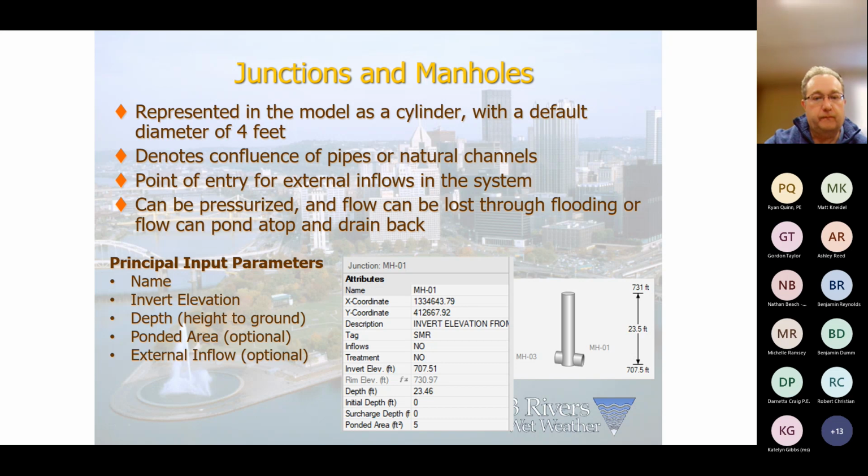When you're working with storage nodes, it has a single place where you mention the rim, so to say. So there you are going to work out your surcharge depth and then put that as your manhole depth. So there are no distinct parameters for rim elevation and surcharge elevations. When you're working with storage nodes, there's a single value that you need to work out.